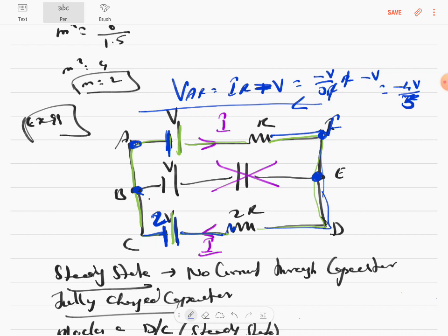And you know that there is a capacitor's potential, which is an unknown potential X. If you come from the right end to the left end, you don't know whether the potential is positive or negative, so just write it. It's minus 4V by 3, which should be equal to, when you come from right to left, from positive to negative, a minus V plus an unknown potential X.